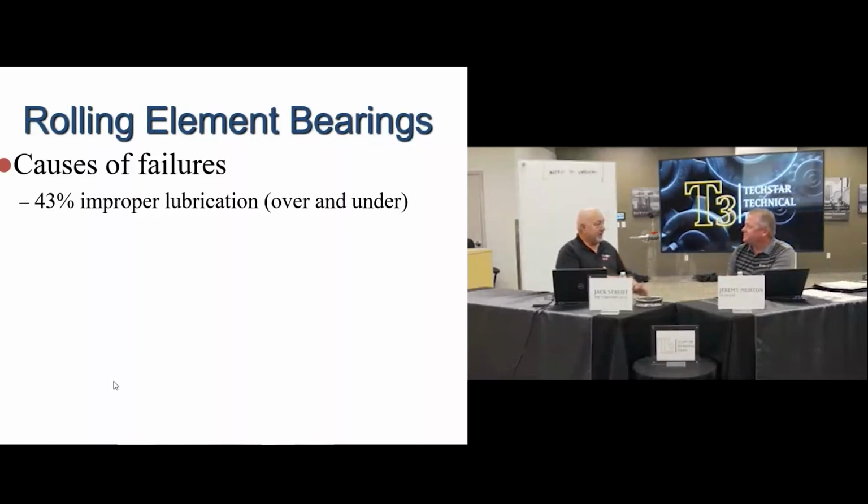Before they even started up, they just started pumping until it was greased up. A lot of these pillow block bearing housings have a drain plug, and they can also be used with oil. The proper way to initially start a new bearing with grease is to pull that plug and pump grease in until you see grease there. That way you're not pressurizing the housing full of grease, causing pressure and friction inside to heat it up. This way you've got the right amount of lubrication in it, put the plug back on, and it's ready to go.